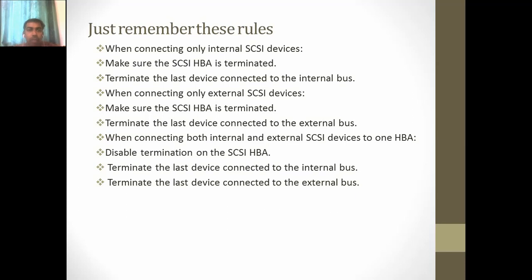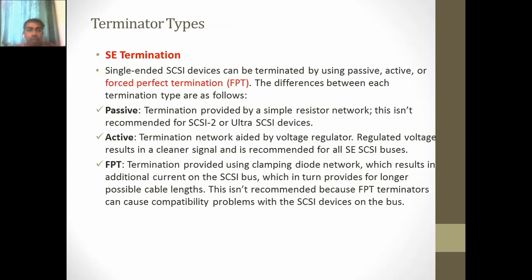Make sure that the SCSI host adapter is being terminated, and also disable the termination on the SCSI host adapter. Terminate the last device connected to the internal bus. Also terminate the last device connected to the external bus. So internal and external bus are the important concept here. So terminate both.